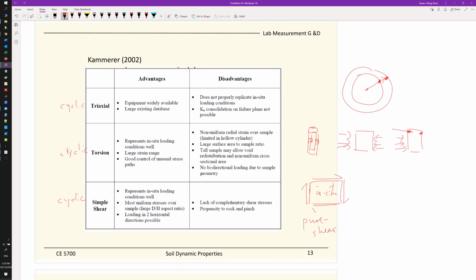But in the lab, when we want a simple shear, we can impose the shear stress from the bottom or the top, and on the other part we can have frictional porous stones or porous media. So you still have the friction right there, just like in the field. But the whole soil sample will be wrapped up by a latex membrane.